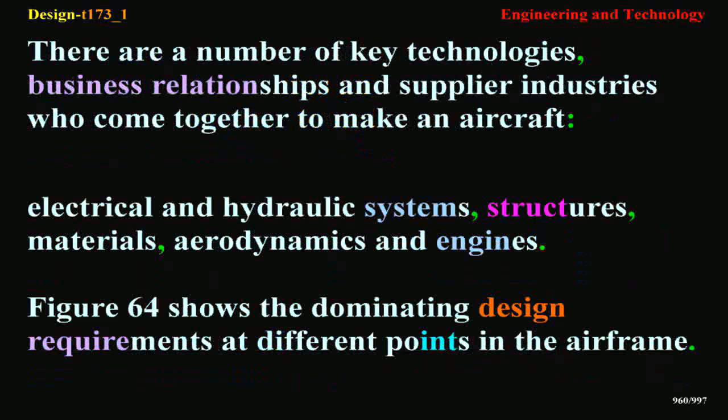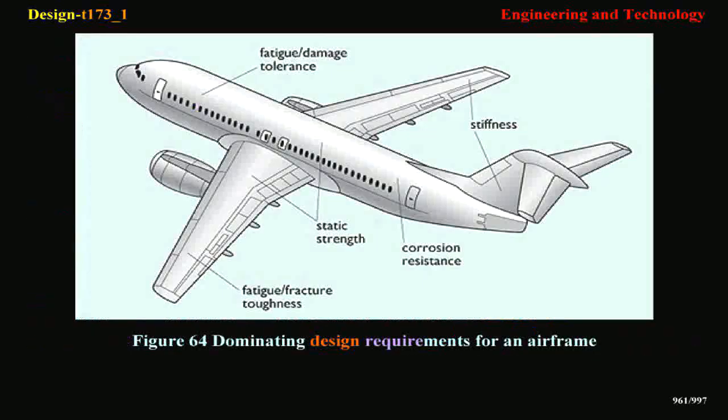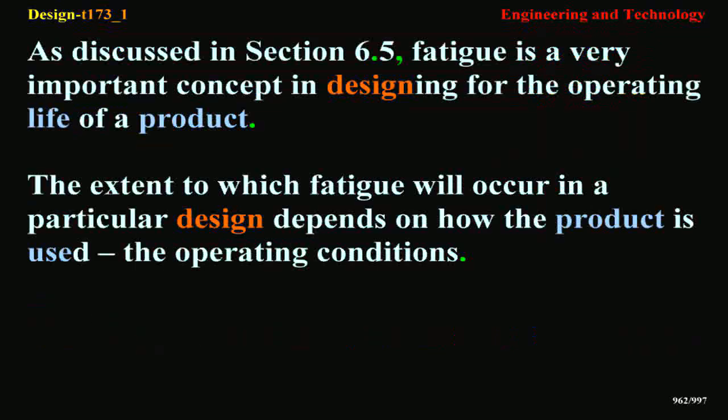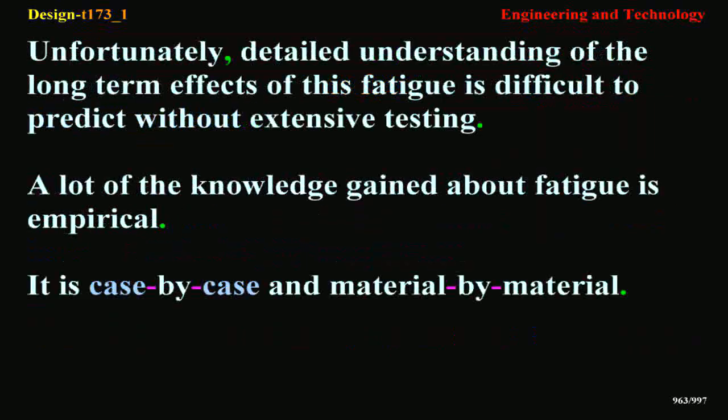Figure 64 shows the dominating design requirements at different points in the airframe. As discussed in section 6.5, fatigue is a very important concept in designing for the operating life of a product. The extent to which fatigue will occur in a particular design depends on how the product is used, the operating conditions.